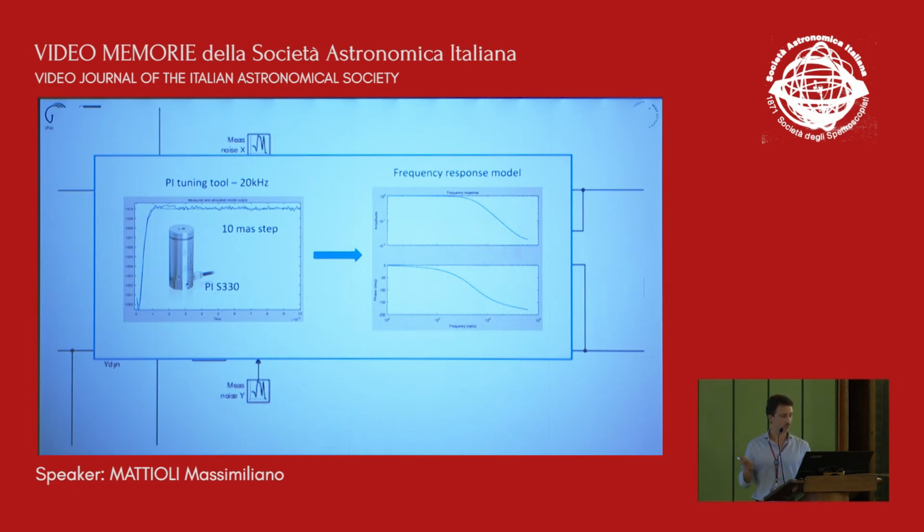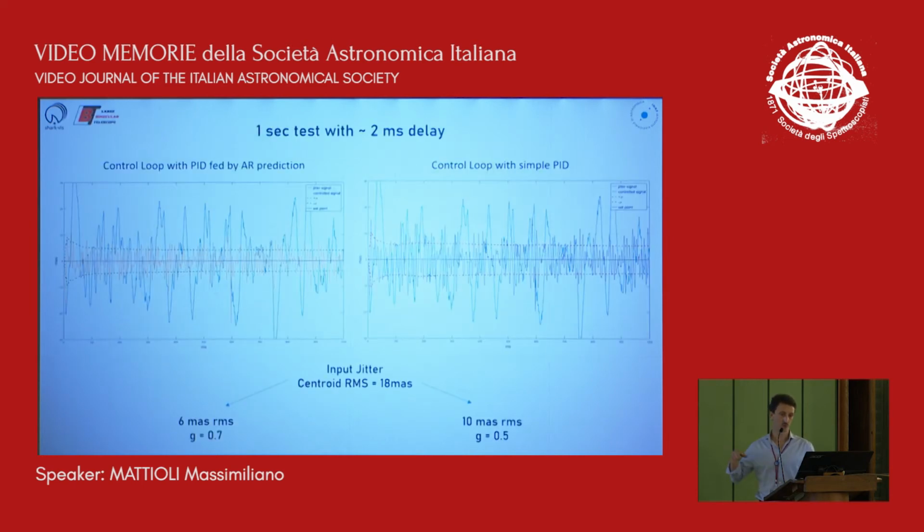Thanks to that tool, we can retrieve the behavior of the piezoelectric stage, which has an internal loop of 20 kilohertz. So we acquired the step response of the piezo tip tilt, and then we retrieved the frequency response model to import into the system.